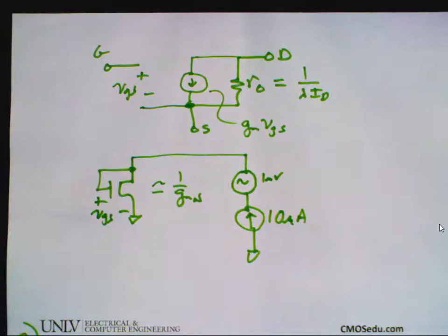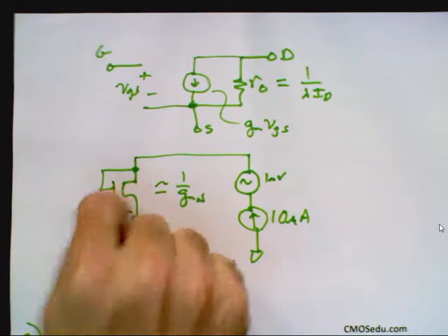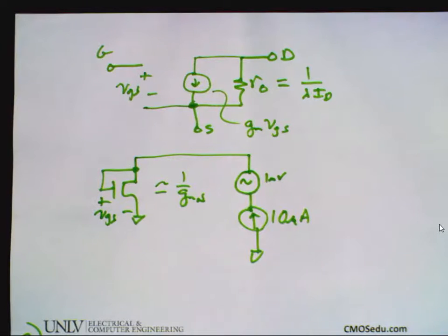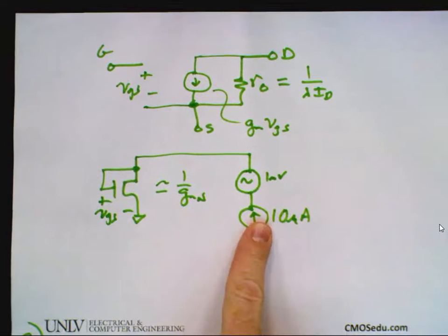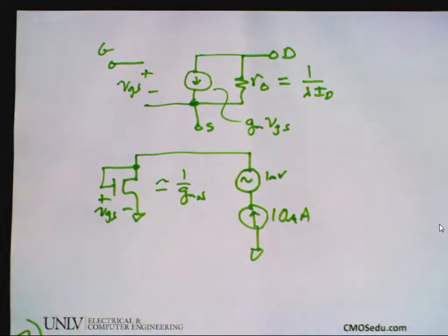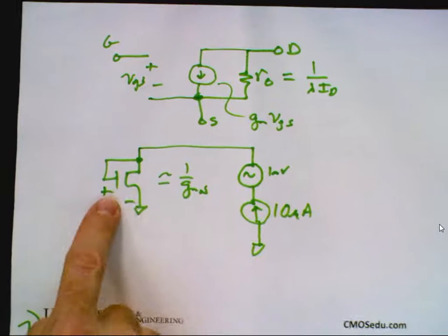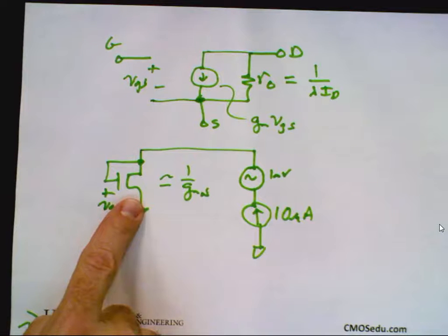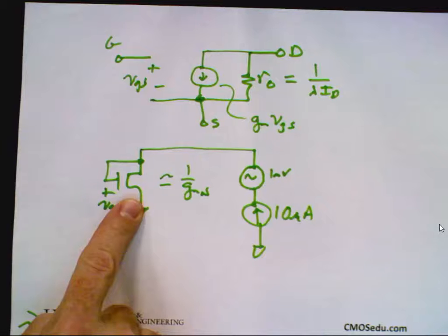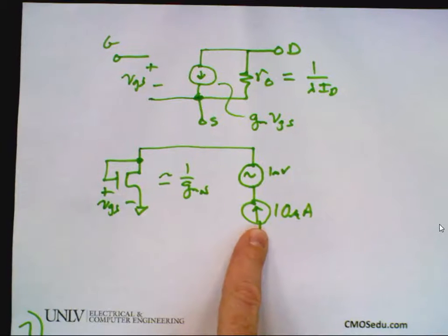Okay, what's the drain current flowing through here? Okay, this is a trick question. It's a trick question because I got a current source right here, right? The current in that circuit's always 10 microamps. I can never change it. So if it's always 10 microamps, what can I say about the AC VGS, or how much this VGS changes? It doesn't, because the current is always constant.